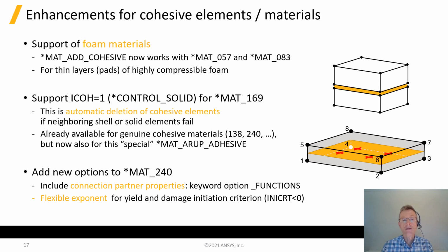There have been some developments in terms of cohesive elements and materials. Certain foam materials can now be applied to cohesive element types, so you can model sandwiches with a thin layer of compressible foam. There's also a feature on control solid.